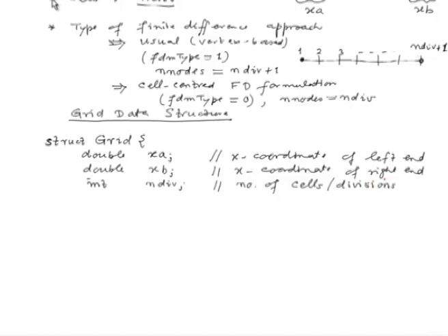We have assumed a uniform grid, so we will have a single parameter which denotes our grid spacing, dx, which we will use very often. So, we can introduce a new variable of the same name, double dx, this gives us the grid spacing. Which other input data should we put as part of this grid?